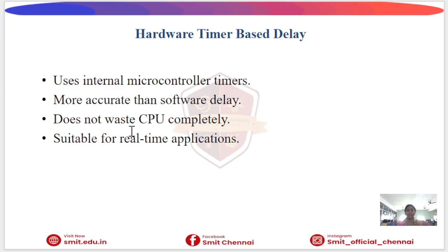If we generate an accurate delay, the system becomes more accurate and suitable for real-time applications. This is the professional method. In industry, hardware timers are preferred; only if some requirements demand it is the software delay used, and its efficiency is lower compared to hardware timers.